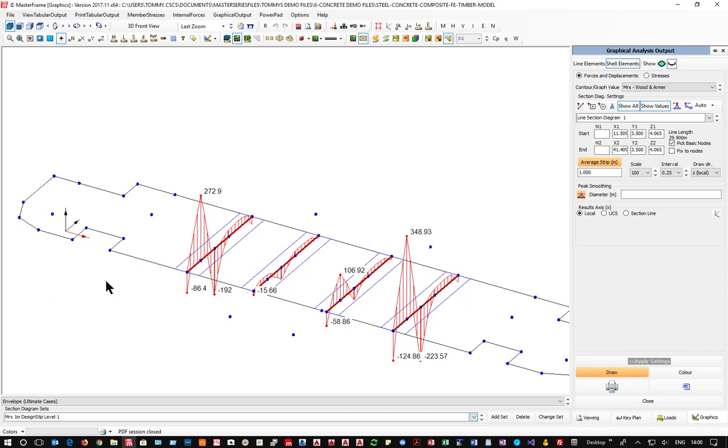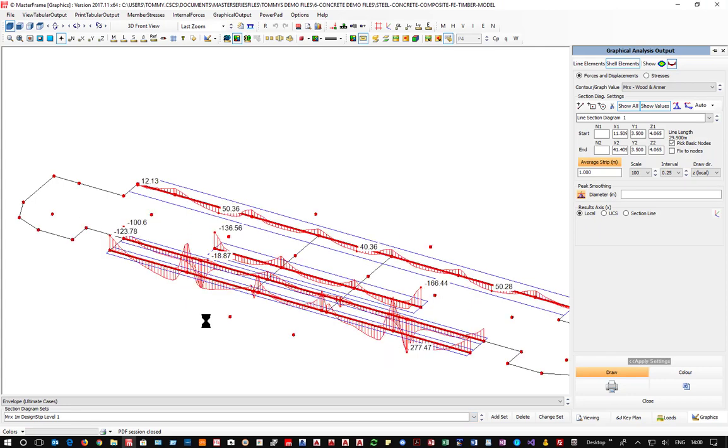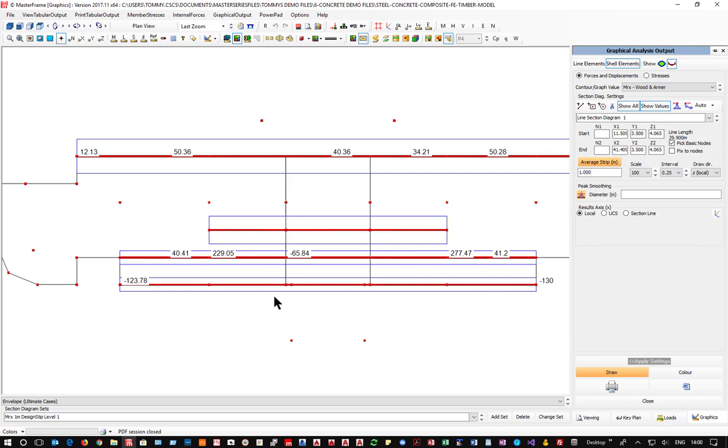So let's look at the MRX. So that's the ones in this direction. It's doing some calculations, as you can imagine, and it's basing it on some strip averages. So if I go like that, you'll see that you've got a strip and then another strip where you have an additional, and then another strip. Now in reality, that's a sagging mid-span strip, and that's the hogging over the columns, because that's columns from above rather than from below. So it's this one and this one, but that is still a useful bit of information.